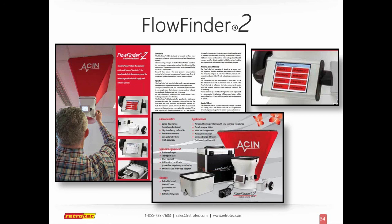And we actually have been checking CFM supply and return with passive flow hoods. This is a powered flow hood. It actually has a fan in it that can create the resistance and give you phenomenally accurate readings in just a few seconds. It's easy to use. It's incredibly lightweight. So if you're really looking for something that can test a kitchen exhaust fan, do the ERVs or HRVs, and obviously the exhaust fans you might have in the bathrooms, please contact us and we can let you know how the flow finder works.